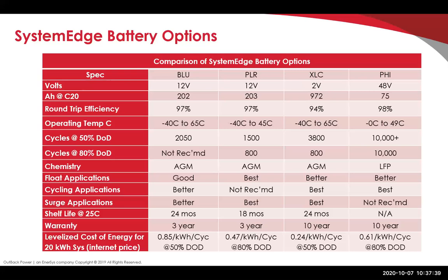To their credit, even with all those cells, they monitor each cell. They have active cooling. As cells start to deteriorate or go bad, they'll adjust the charging voltage, so they really have a pretty sophisticated BMS.